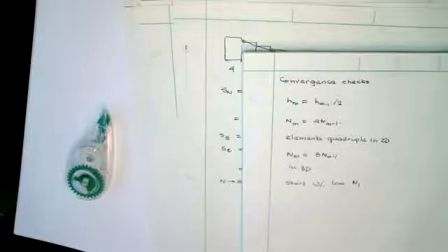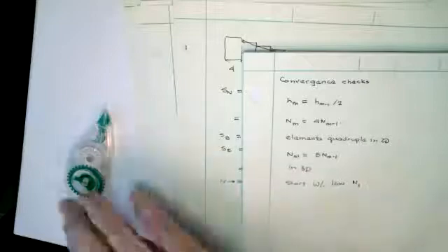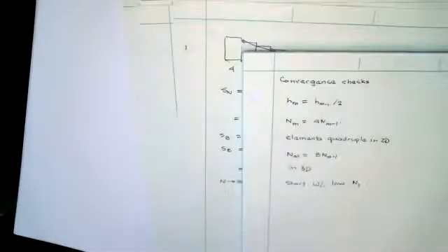But one of the things that happens in practice is people go and build their first finite element mesh as if it's the right mesh to do the problem. No, what you want to learn to do is to build the first finite element mesh that might give you a halfway decent answer. And then you can refine it and see, by the time you get to the mesh that you think's good, whether they're converging or not.